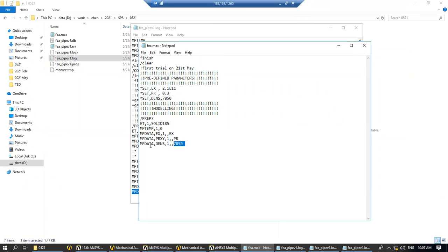And then in this case, I can paste another thing to say this is dense. The small letters and the capital letters don't matter. They are the same thing. Sometimes I use this exclamation mark to deactivate one sentence. This is useful also if you want to play with your APDL.